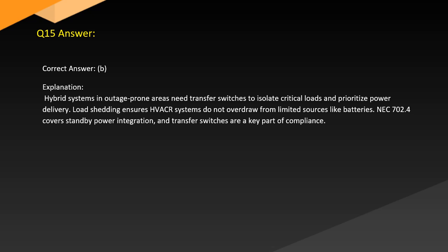Answer. Correct answer: B. Explanation. Hybrid systems in outage-prone areas need transfer switches to isolate critical loads and prioritize power delivery. Load shedding ensures HVACR systems do not overdraw from limited sources like batteries. NEC 702.4 covers standby power integration, and transfer switches are a key part of compliance.